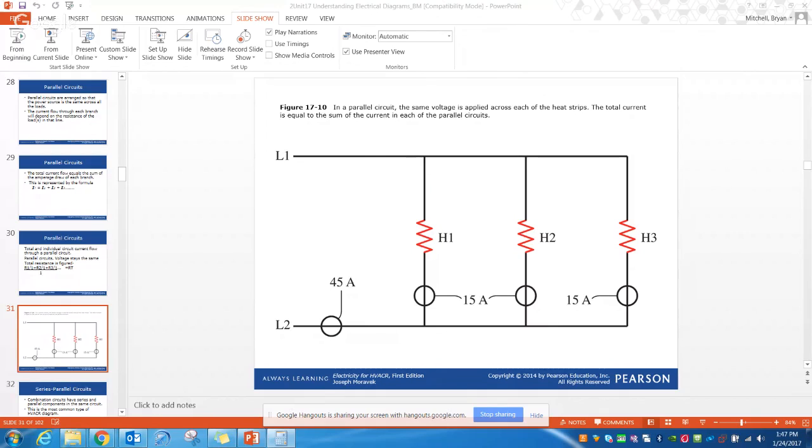Now we know, since we have 3 resistors in here and they're all equal because they have equal current drop off of them, that we're going to be able to take this 0.18 and push it up into 3 equal sections. So 0.18 divided by 3 in this case equals 0.06.